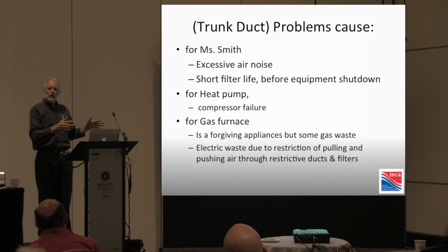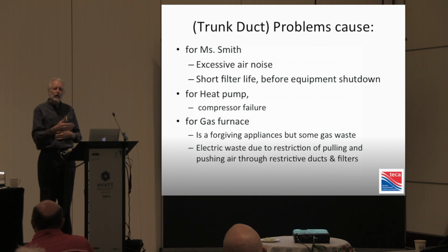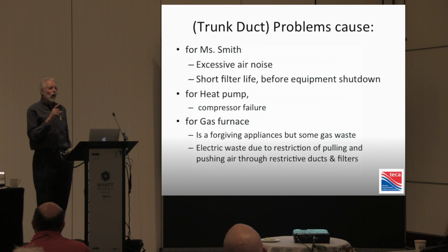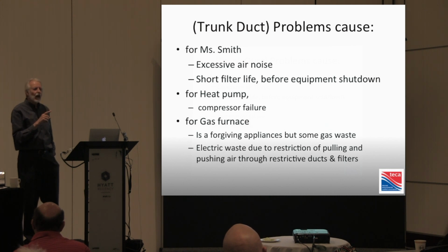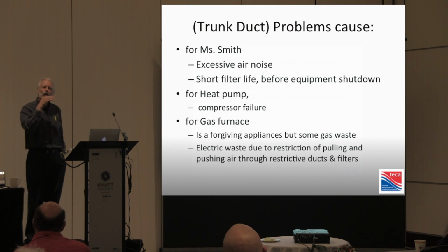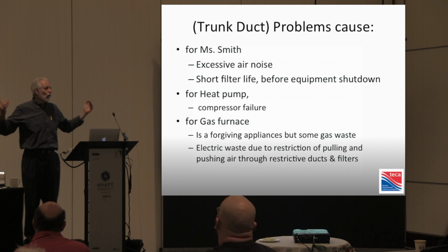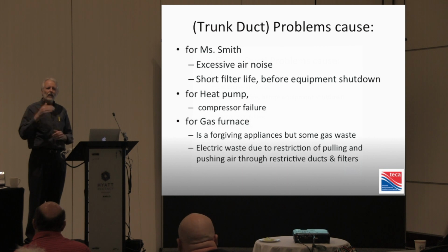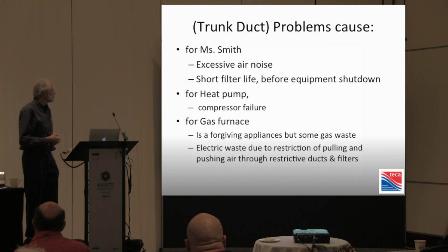So if you have a ductwork system that's really horrible and has a high degree of resistance, and then you put a filter on top, you can't get any degree of filter life out because it barely starts to get dirty, then you've got to turf it. This was okay in the days of horsehair filters and fiberglass filters, but when Mrs. Smith wants a better filter, it means she's only able to skim the top 10% off her filter before you're at risk now of high limiting that appliance for inadequate airflow over it. So essentially it shortens the filter's life way below what the manufacturer has rated it for.